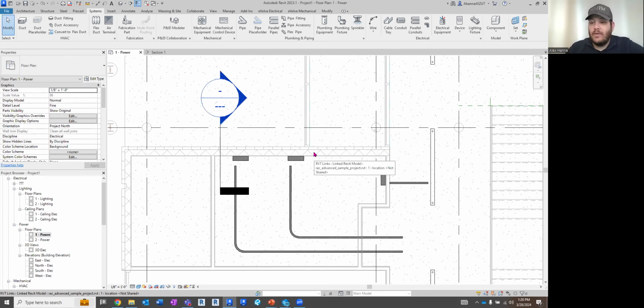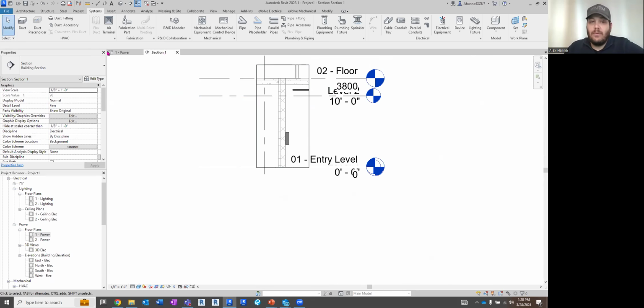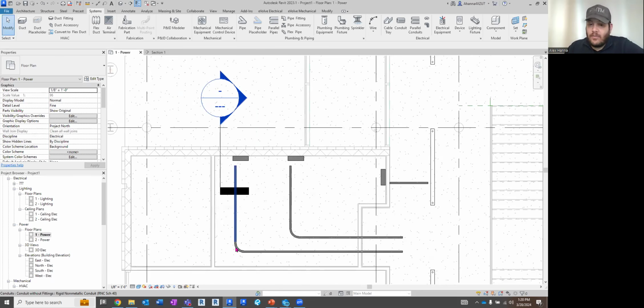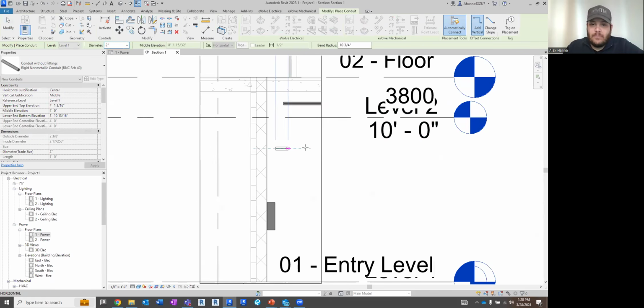Back to modeling conduit in 3D. So coming through here, I opened up my section view. I dragged my conduit up. It did drag the full elbow around as well because all these are connected. They're all the same height. And if I wanted to draw my conduit down, if I take this piece of conduit, I'm just going to draw another one here.